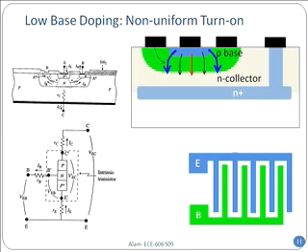And those high-powered transistors have emitter and base essentially interdigitated, so that you do not have one big chunk of emitter and one big chunk of collector. It is all interdigitated so that the distance between emitter and base is always minimized, and that way you do not have too much resistance between them. So this is a solution all modern transistors would have because of this base doping issue.